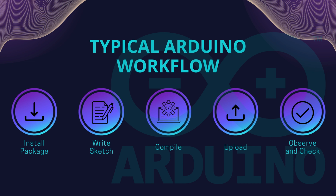The next step will be uploading the compiled sketch to the board. We need to ensure that the right port is selected and other information is configured according to the board we are using. The last step will be, after uploading, we need to observe and verify physically if the system behaves and works appropriately.